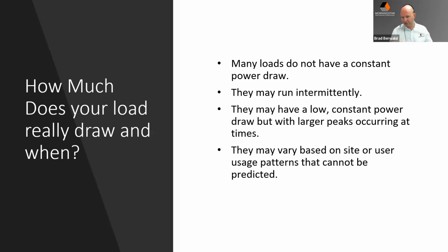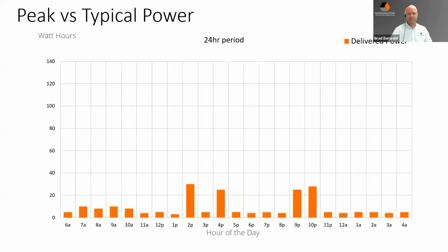They may have a continuous power draw as they stay on, and then they might actually peak or spike in power that may not be accounted for, because depending on how often you log this data, you may not see those occurrences unless you're looking at it literally every few seconds. So keeping that in mind is extremely important. And then also the usage patterns of the user sometimes can impact things. If they understand what it is they're connecting and how much it draws, which many do not, then it can actually help them to create better systems in the future.